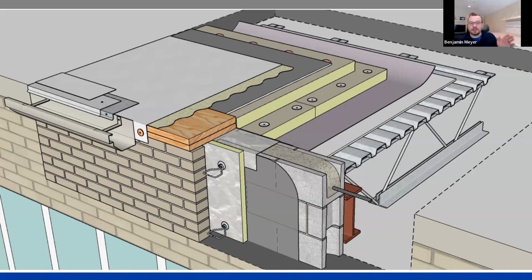And what you see, and we talked about it being that close to that ideal condition, so it's flush on the wall to the roof. You have a nice corner that has the gutter. But in order to actually build that, the structure is not ideal. It's got a little bit of a bump up where the bond beam comes up and creates room for all that roof insulation. So we have an adhered single ply on a cover board with insulation below that adhered, and then a vapor retarder down below.